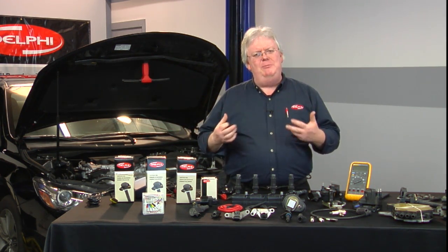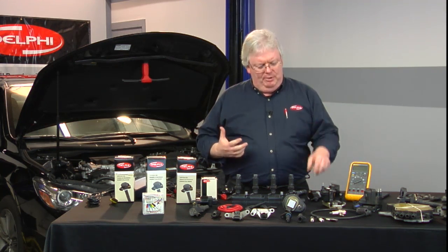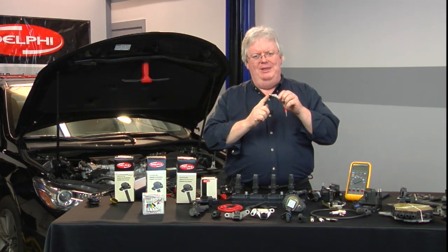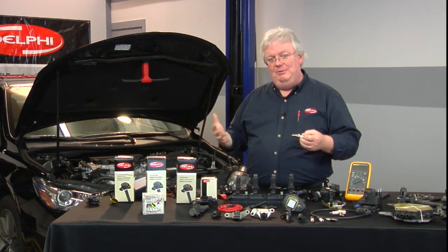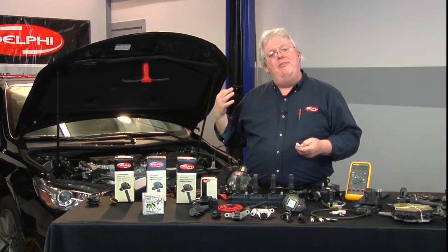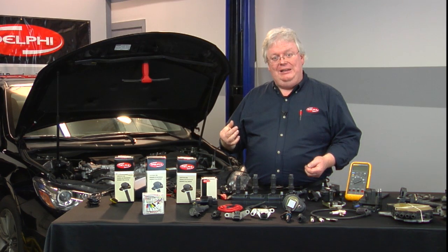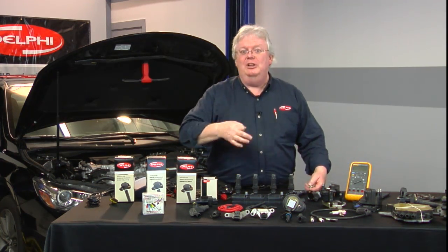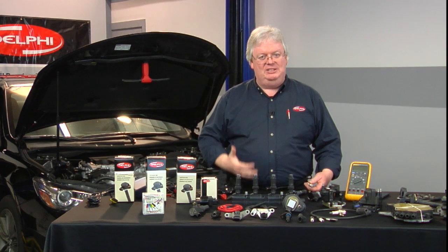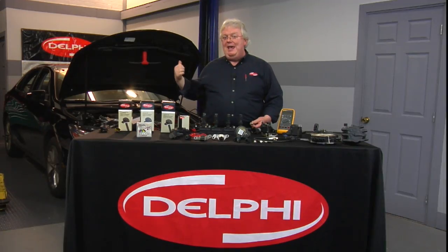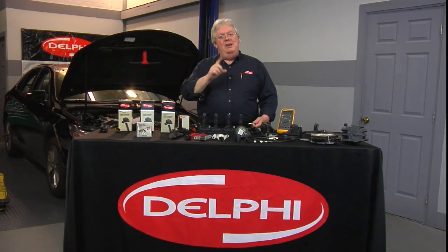When you have an ignition misfire, that's going to be a lot of unburned air in that air gap that never got burnt. So as it went out the exhaust valve, it got across that O2 sensor, and the O2 sensor saw a very lean mixture. It wasn't really lean, it was just a lot of unburned air from a cylinder misfire, ignition-related misfire. A lot of unburned fuel makes the cat hot, but the O2 doesn't care about that, it only measures O2.